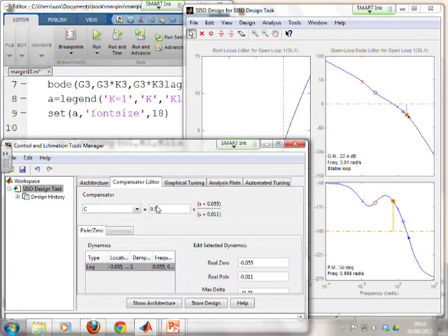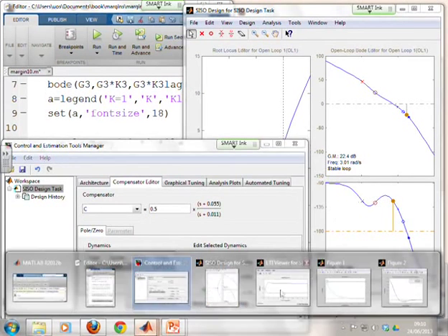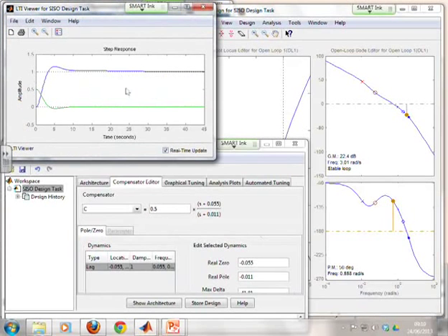So there we go. And what do you notice? Again, we've got our 56 degrees, which is about 5 degrees away from where we started, because we're using beta of 5. You see this classic phase dip to the left. And if I just pull up the responses, again you see this rather slow settling that you get from the lag compensator, because I've introduced this very slow mode.